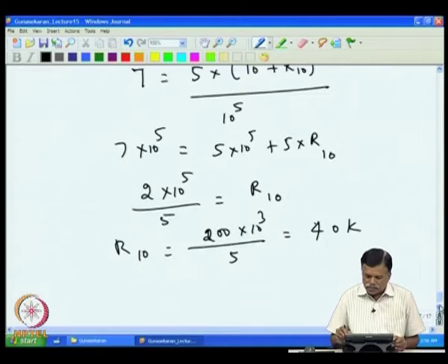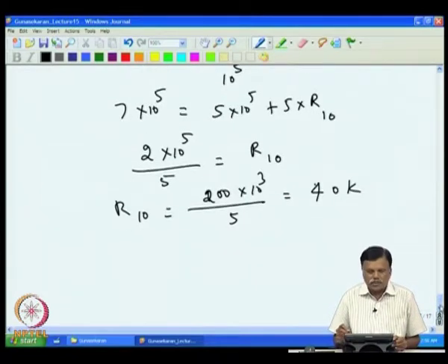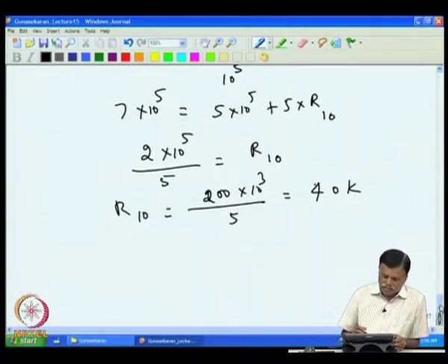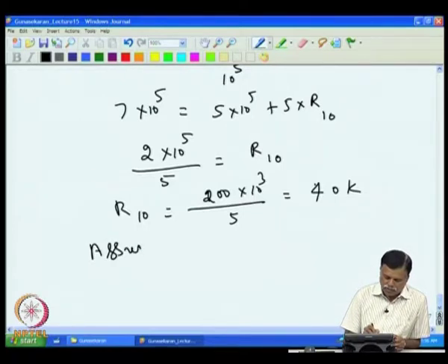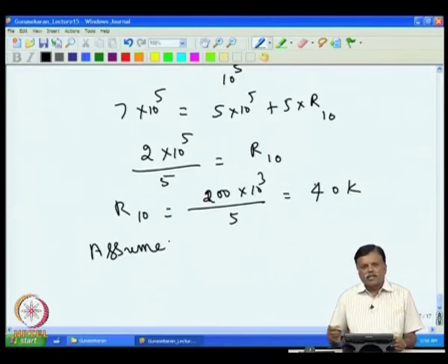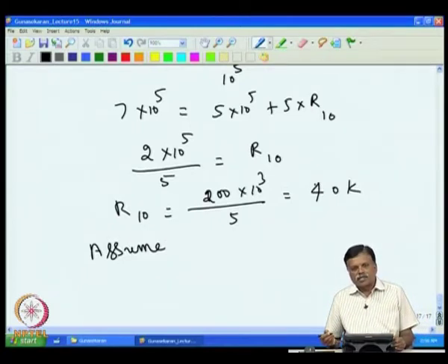Now we fix the drift. Assuming we use 50 ppm resistors, it can be 25 ppm or it can be 10 ppm, depending upon the drift that you are looking for.